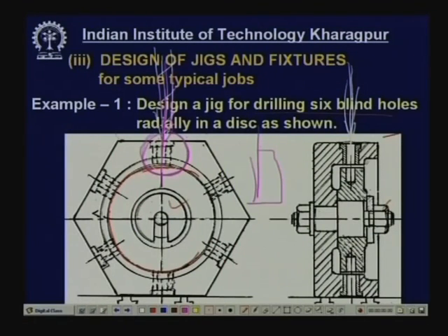Anyway, the axis of the drill and the axis of the hole to be made, or the axis of the bush that has been fitted to guide the tool, should be aligned, and this is mostly done manually. After the hole is completed up to a certain depth, governed by a stop, the drill will be withdrawn. After the drill is withdrawn, what next is indexing.